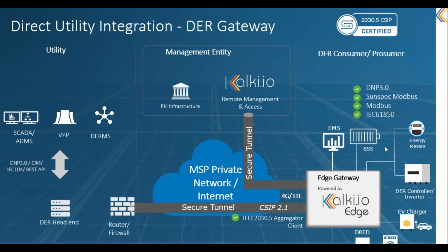We can also connect with the energy storage systems or the EV charging systems directly on REST or Modbus or different other proprietary communication links. For the DRLC, demand response and load control can be done through Thread devices, which are used to connect with the gateway, and the Thread will in turn connect with the appliances, the consumers, and control these devices directly.